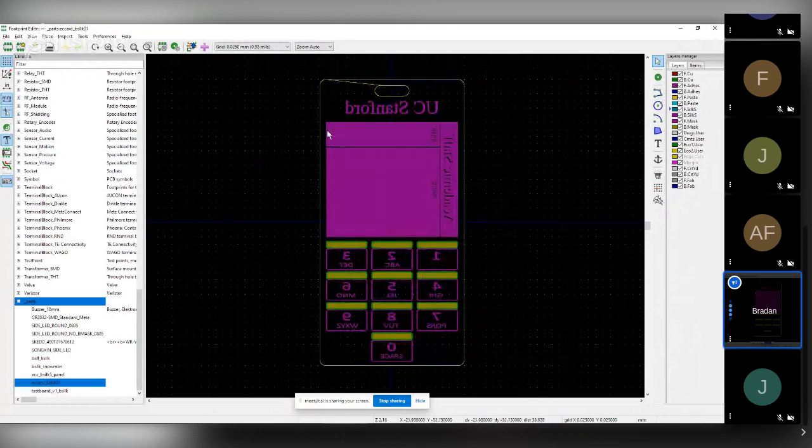So I've opened up that footprint that we just generated, and you can see down here, I'm removing copper, I'm removing mask, I'm doing a bunch of different things. There's this extra little line. So if you do a hole within your edge cut, this is the only mistake that I found.